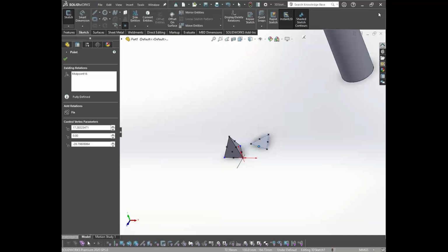The actual results are what you get on site, where the actual loading and different types of vibrational or actual loading conditions are occurring. So why we use FEA: since we are not getting the actual result, the purpose of FEA is to get values closer to the actual values that are happening. If you introduce more elements in your model or in your geometry, you will get closer to the actual value.